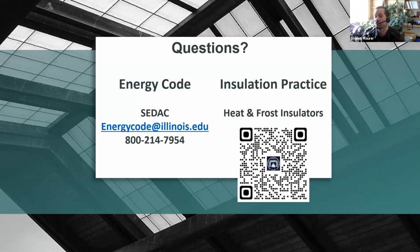So yes, if you're going to go with an insulated stud cavity, it's better to build another interior cavity or chase to have your insulated plumbing and other utilities run through that interior stud wall. Or alternatively, you can start going more and more toward exterior continuous insulation and leave that stud wall open for those utilities without filling it with cavity insulation, or giving you a little bit of leeway in the performance of that cavity insulation.